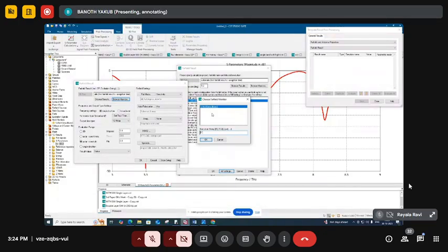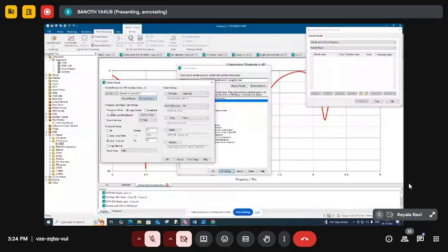For this antenna design, I selected the far field broadband first. I already showed that I selected far field broadband and transient broadband. That option is shown here. Just click on the far field broadband and select. After selecting, just click OK. Here also, after selecting the browse monitors, the frequency setting asks for single frequency by time or broadband. Just select broadband and go to the evaluation range.